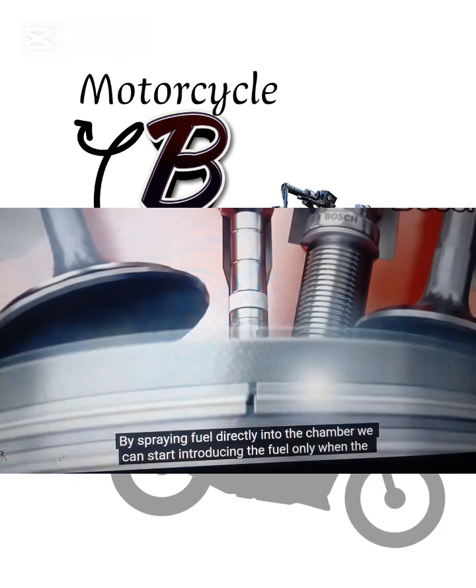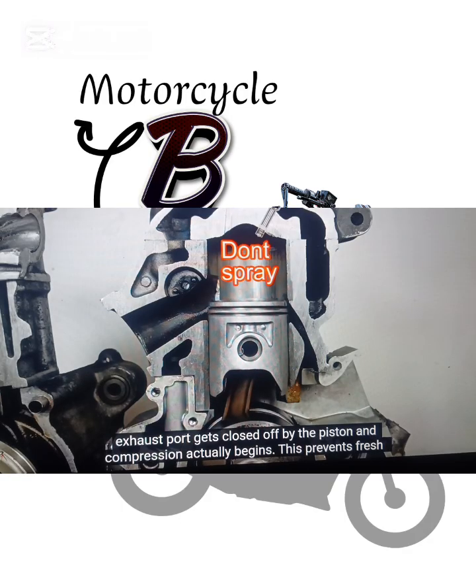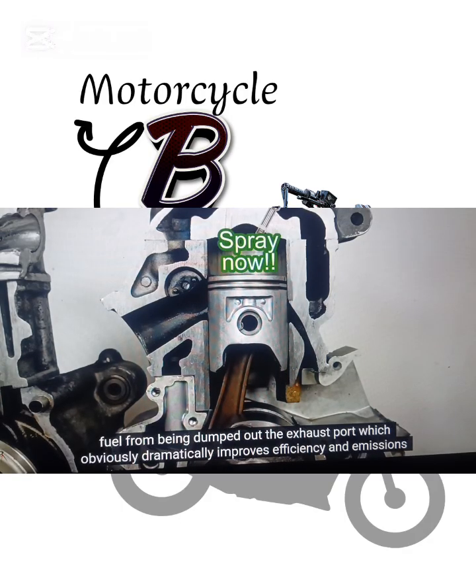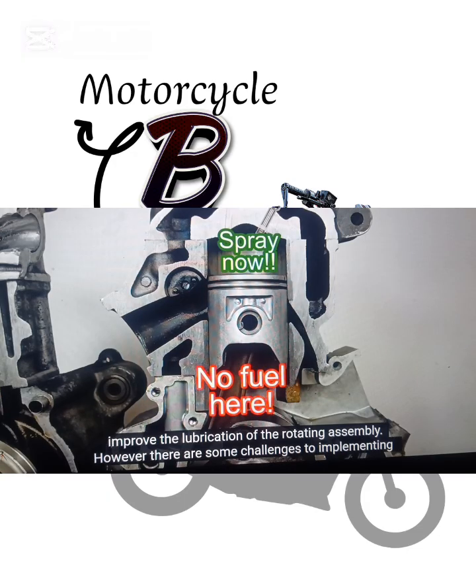By spraying fuel directly into the chamber, we can start introducing the fuel only when the exhaust port gets closed off by the piston and compression actually begins. This prevents fresh fuel from being dumped out the exhaust port, which obviously dramatically improves efficiency and emissions. It also removes the solvent properties of fuel from under the piston, which can help improve the lubrication of the rotating assembly. However, there are some challenges to implementing this technology, and it's still in the development stage, and only time will tell if and when it will become a mass production reality.